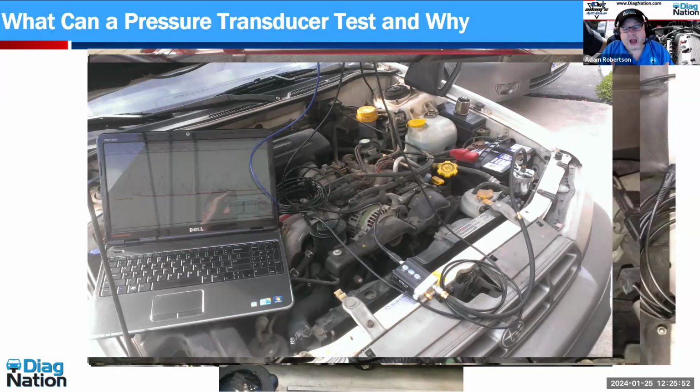But here's what I found, and this was freaking cool, and it was by accident. So I noticed that when I had my pressure transducer hooked up to the radiator, like you see right here, the cooling system, if I rev the engine up and let it off, and rev the engine up and let it off, provided it has a belt-driven water pump, obviously, then I would see what looked like a cam sensor. It would have a positive pulse, negative pulse, positive pulse, negative pulse. So it would go through this positive, negative, positive, negative as it sucked a little bit and pushed back out and sucked a little bit. And I'm like, wow, I'm seeing my water pump work.